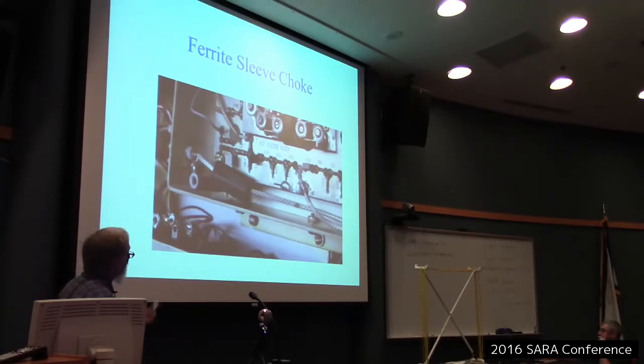Okay, superset. I'm going to talk about that in just a little bit here. So that shows that whenever something strange seems to be happening, if you touch the outside of a cable or some areas near it and something strange happens, try it, because you can get those ferrites on a clip-on thing, and they're not too expensive now. You can clip it on, and if problems suddenly go away, just leave the ferrite there.